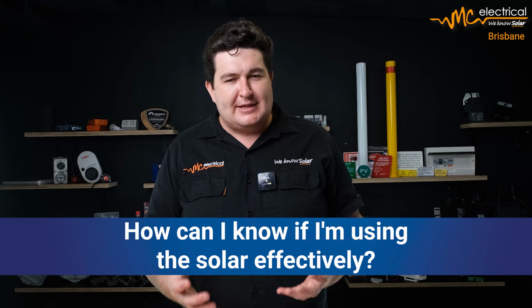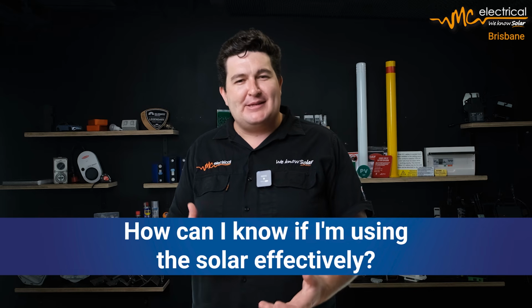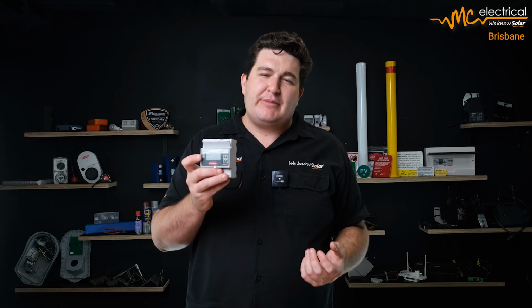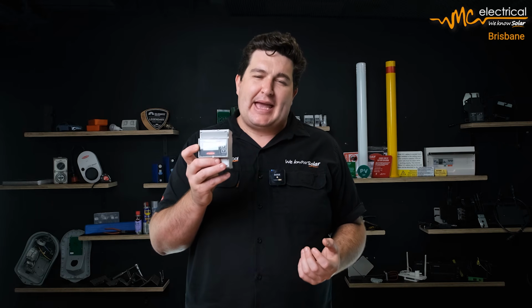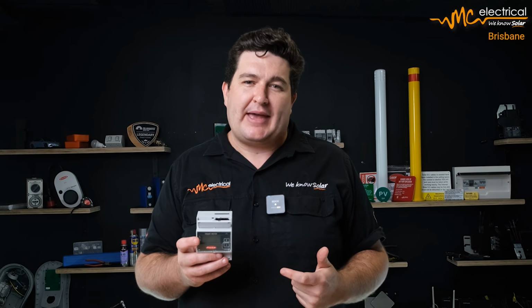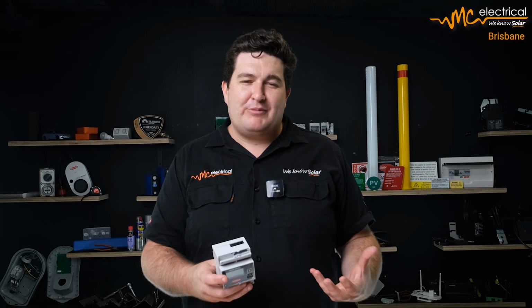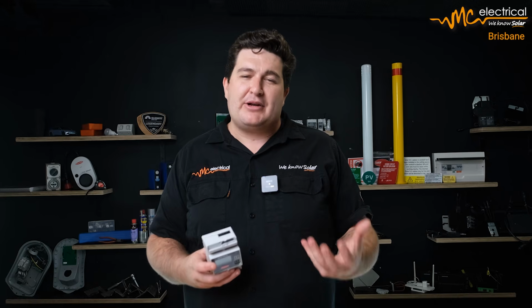Talking about consumption monitoring, how can I know that my solar system's working well? How do I know if I'm using the power effectively? Well, one of the things that we can add with an inverter, and pretty much is done with all systems today, is a consumption meter, which measures the power that goes to and from the grid. So the inverter knows what it's producing, it knows what's going to and from the grid, and from the difference between those two amounts, it can calculate how much power you're using inside the house, either to control a battery or just to tell you, hey, you're using your power from the solar, or you're using it from the grid, and how much is coming in and out.